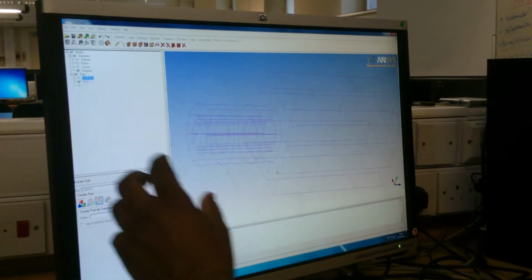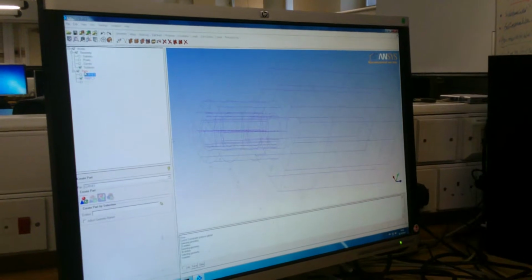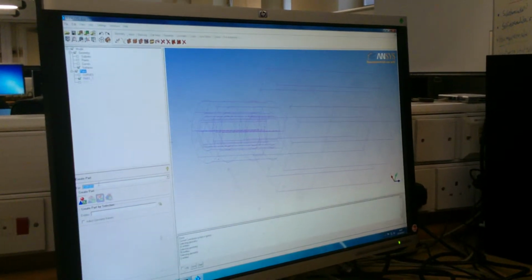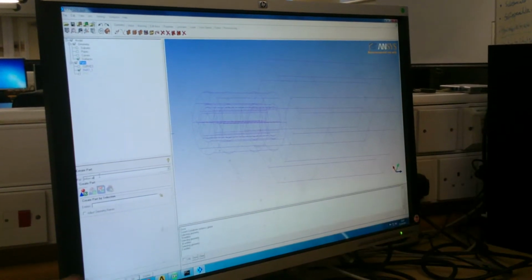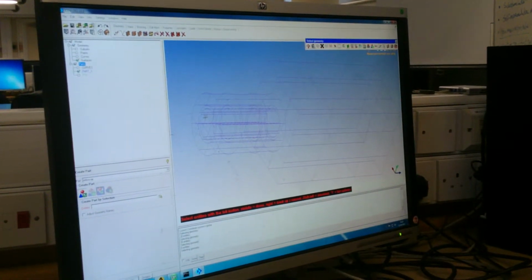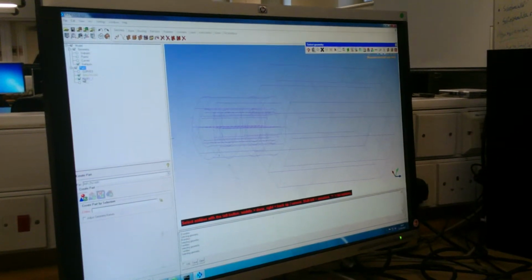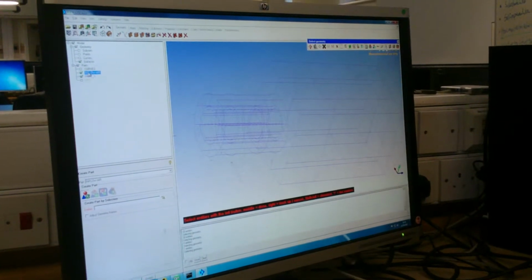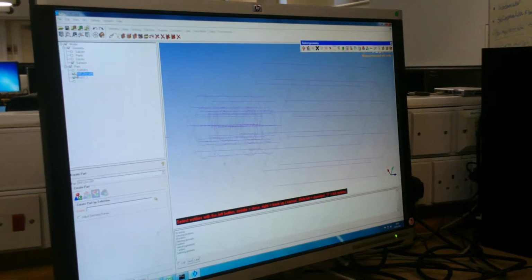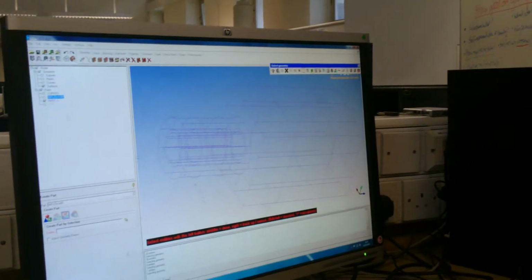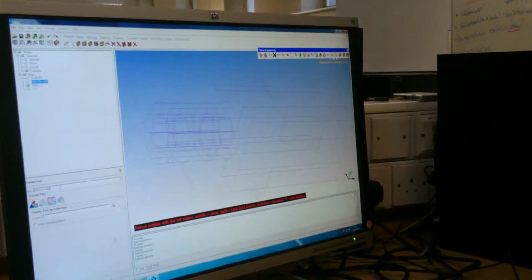Now, do you remember we said the air will come from here, right? I will create another part. Click, if it is there, create a part file. I will call it inflow air, where the flow of air comes in, and then I will take this one and select exactly where the air is. Right? You see, inflow air. Let me check the color because the color looks bogus here slightly. Right? You see the inflow air. Put it on, and then again I have inflow fuel. Right?